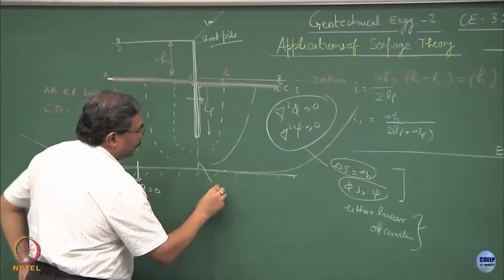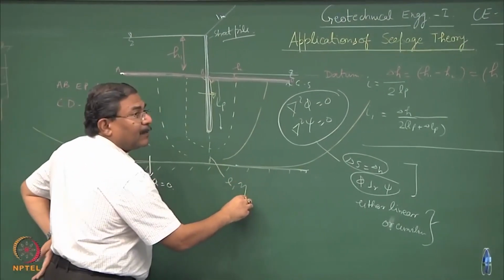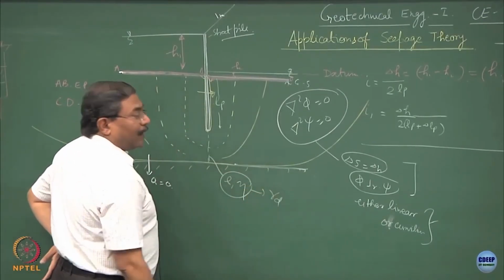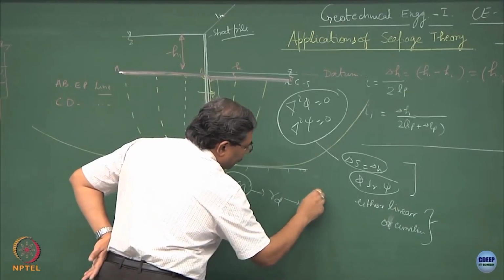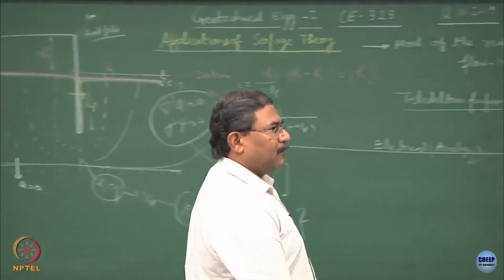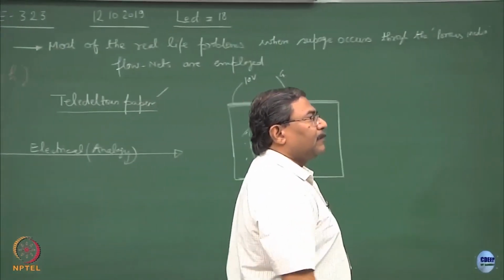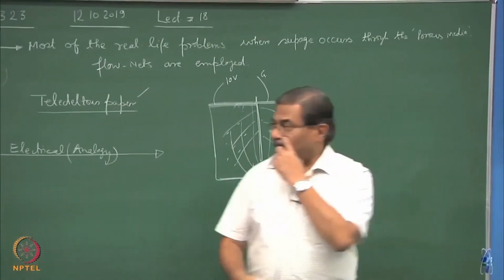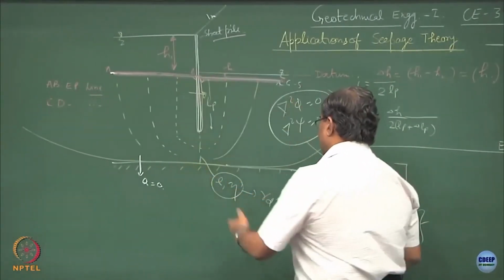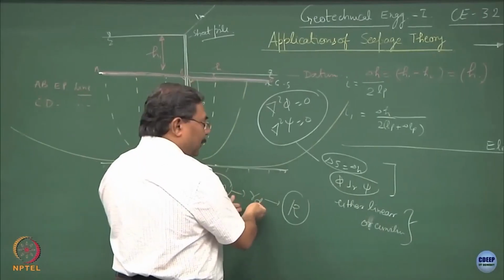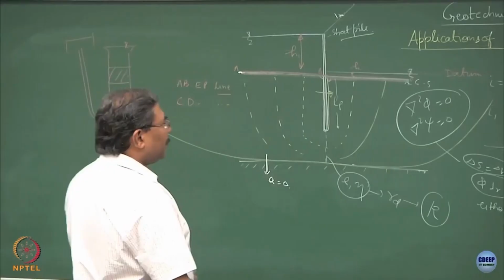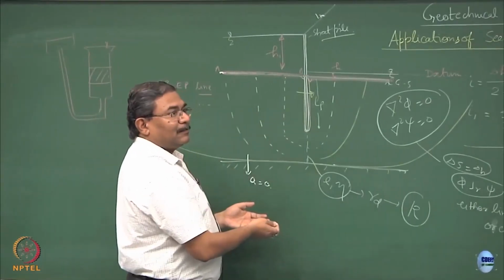Ultimately, everything will get affected in the form of void ratio, porosity, and these things will reflect on gamma d, and this is going to reflect on k, that is it. How does it matter? Got it? So, if I do a borehole here before inserting the sheet pile, if I know the profile of the soil, I know the void ratios, porosities, I can compute gamma d, I can relate it to the hydraulic conductivity, that is all. The question is, why are we doing all this analysis?